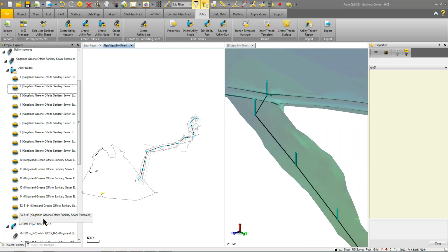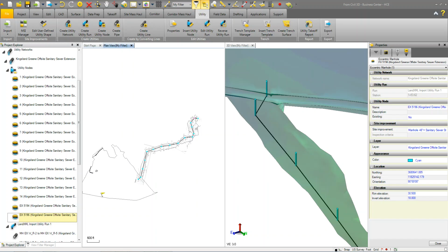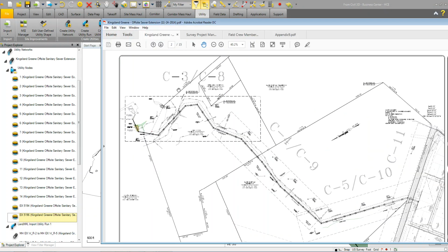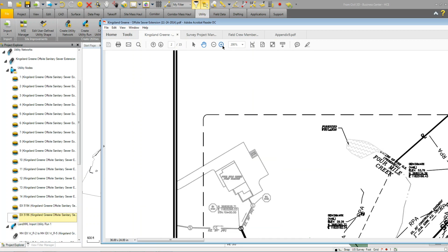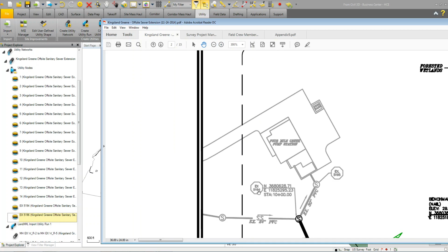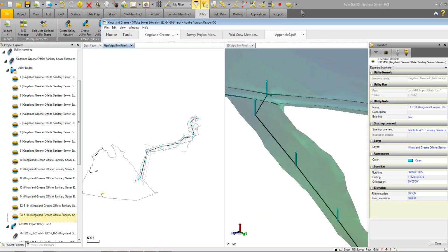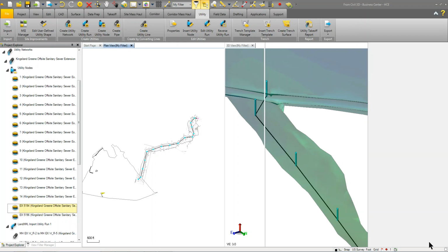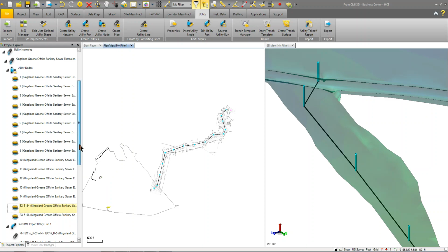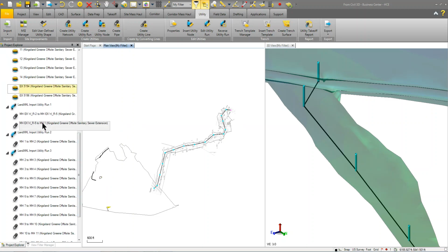The one manhole that is existing, if we take a look at this, we know that this manhole here is existing. That's 5194. So if I come back over here and take 5194, we're going to set that one to existing. All right. The rest of the stuff should stay the way it is. Then we'll come down and we'll work the pipes. So we've got some pipes here.